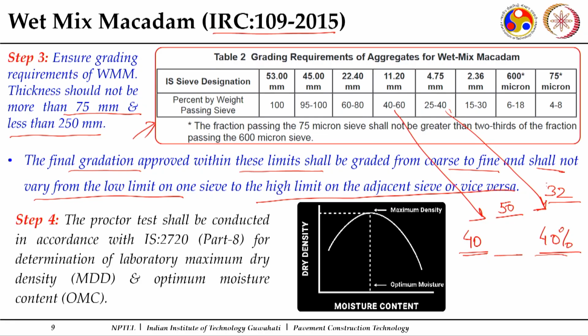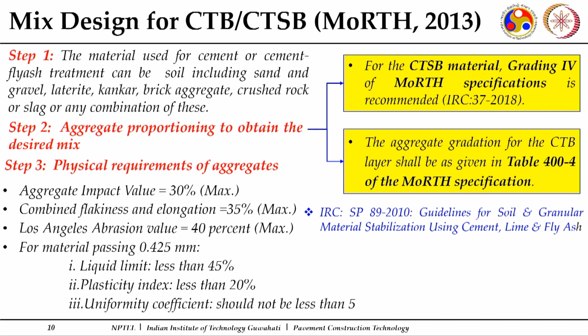And then again, as mentioned, we need to go for the determination of OMC, MDD, and finally the CBR, and from that we get the elastic modulus for use in the flexible pavement design. So this completes the discussion on wet mix macadam.